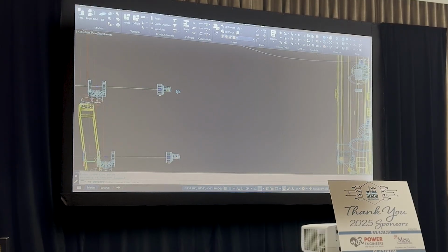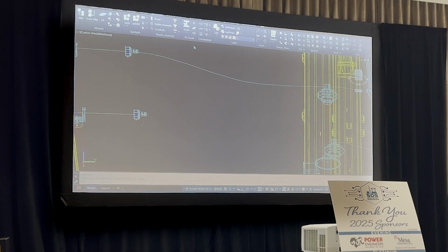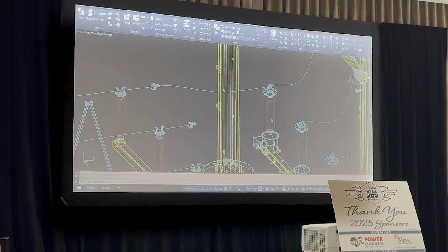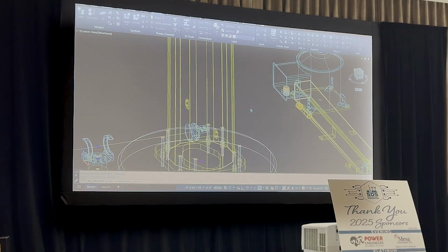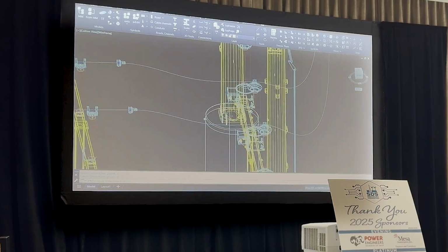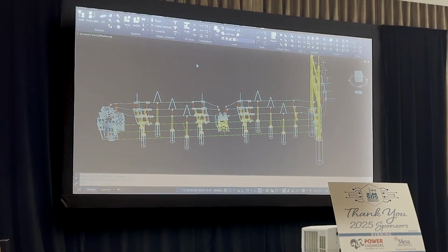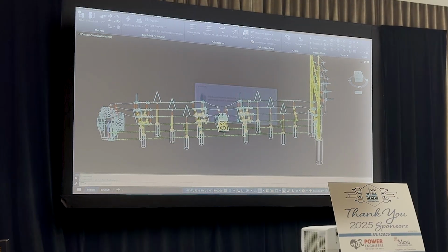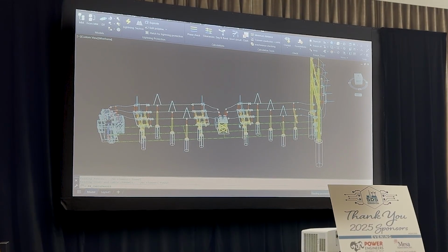And then I could also copy, since that's the same cable that's here, I could also copy this one from here to here. Alright, so now we have bus work around this whole thing. The good check to do before I jump out of this model is I can go to this PR calculations and hit the phase check. And what this is going to do is trace connectivity through the whole thing. So if I missed a connection that I can't connect, it's going to show me here.